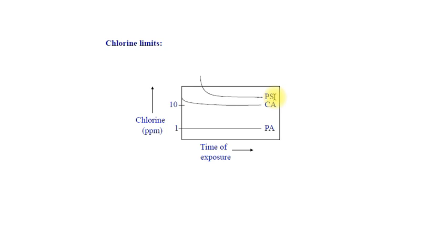So it may degrade your membrane, and that's why we use a carbon cartridge in the domestic membrane-based separation process, the domestic reverse osmosis unit which we use in our homes. It contains a carbon cartridge for removing this chlorine. Because if we directly use the reverse osmosis process for the purification of municipal water, the membrane will degrade or decompose very quickly due to the presence of chlorine.